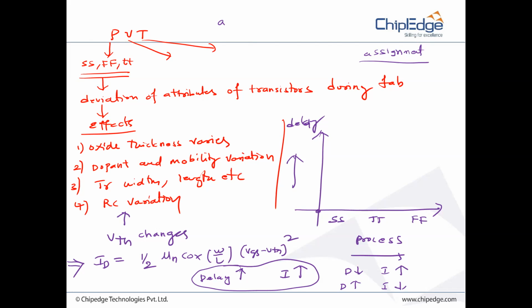It depends upon the capacitor, so input transition and output load. If current is less, it takes more time to charge, right? So delay increases. And if current is more, it takes less time to charge, so the propagation delay will be less. Yes or no?